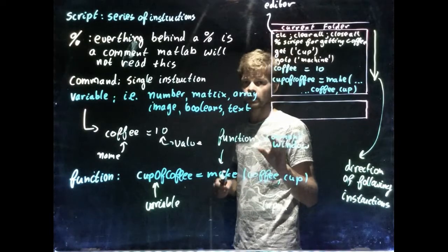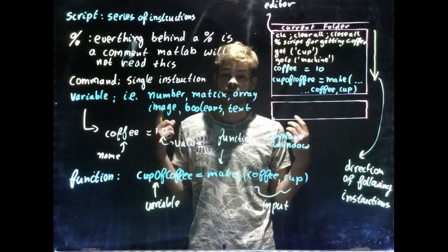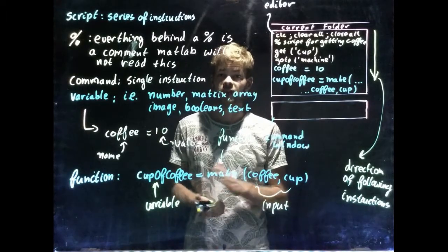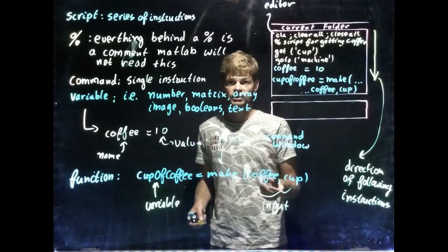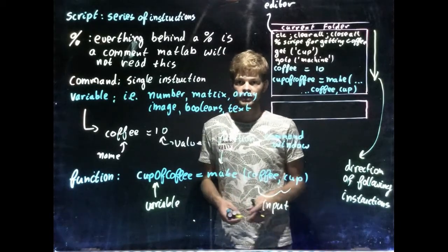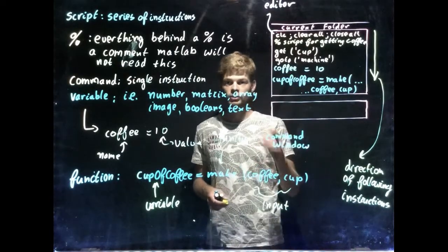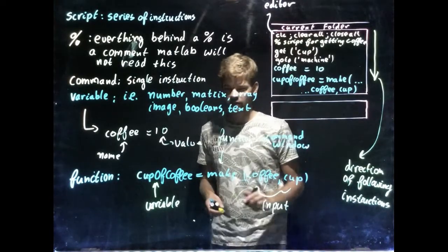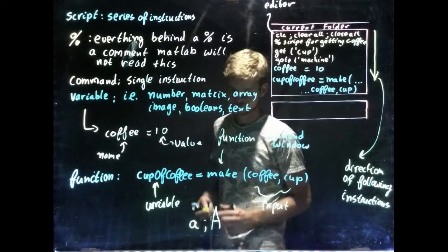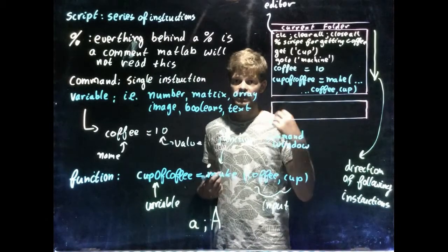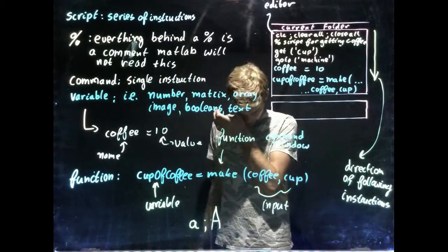I think these are the most important things you need to know. There are many more, and there's even some more explained in the MATLAB reader, so it's very useful to take a look into the MATLAB reader. Mind this: MATLAB is really sensitive to upper and lowercase letters. And every one of you, I'm sure, will find this out the hard way. You will be searching for an error because you used a lowercase letter instead of an uppercase one. So keep this in mind. MATLAB is really sensitive to this.